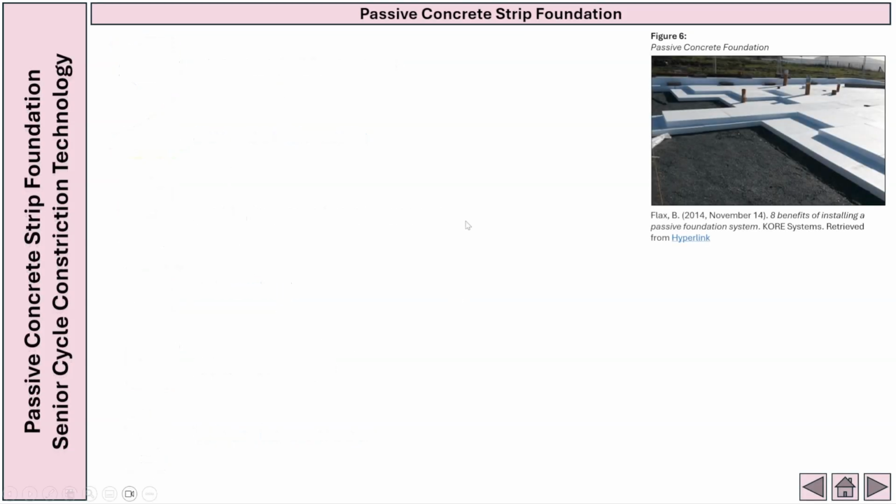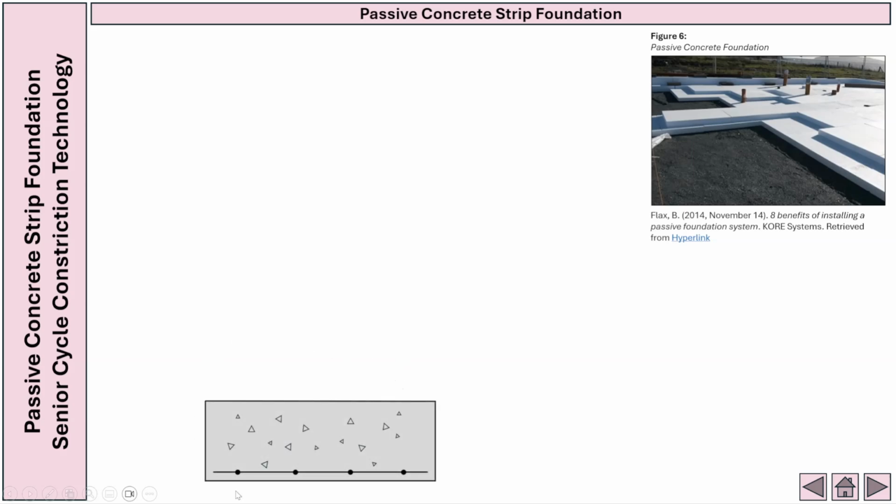As always, before you start drawing, just make sure that your dimensions are divided by 10, because this is a scale of 1:10. What we're going to do is start off with our reinforced concrete foundation, and because the wall structure is going to be a little bit wider, that means the foundation is going to be a bit wider as well. The foundation totals 1350 by 450 and it's reinforced here down below.